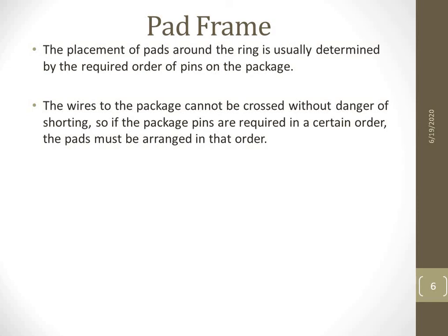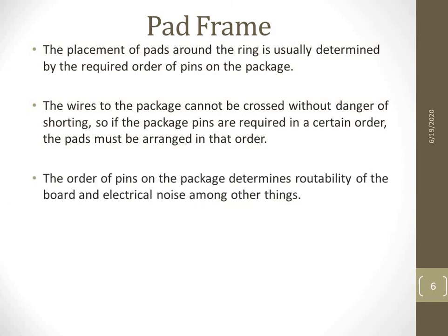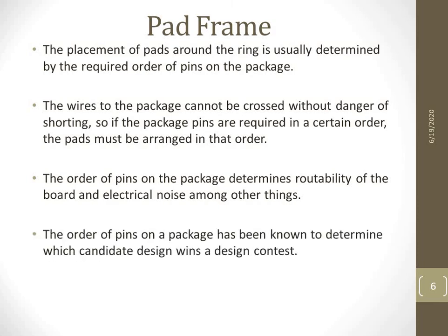So if the package pins are required in a certain order, the pads must be arranged in that order. The order of pins on the package determines routability of the board and electrical noise, among other things. The order of pins on a package has been known to determine which candidate design wins a design contest.